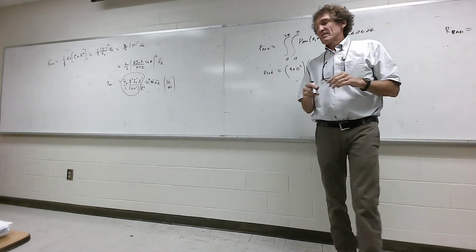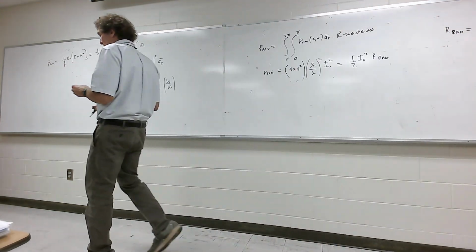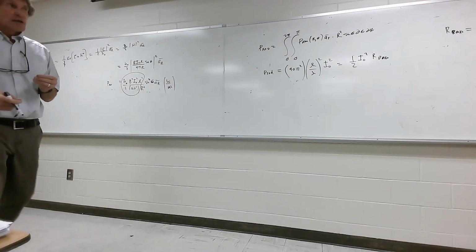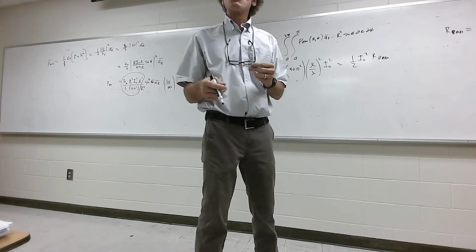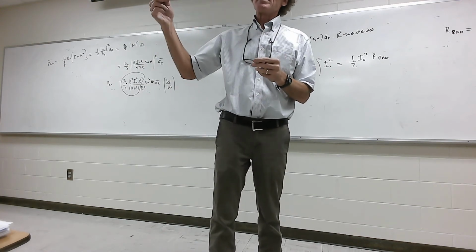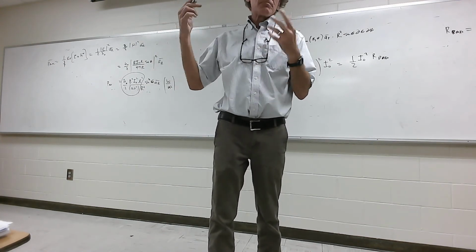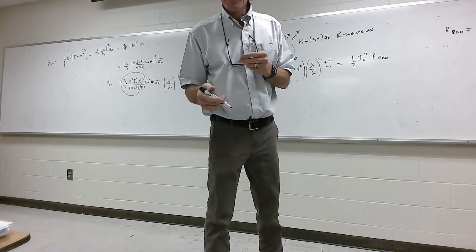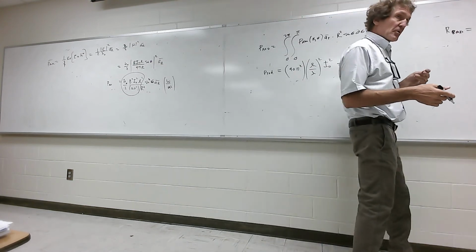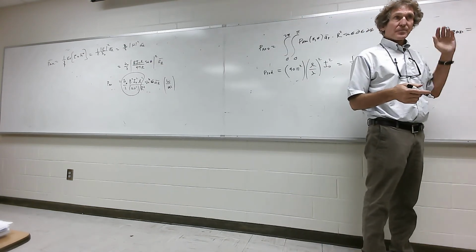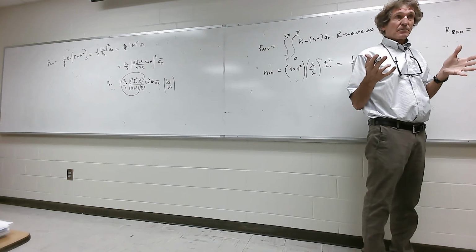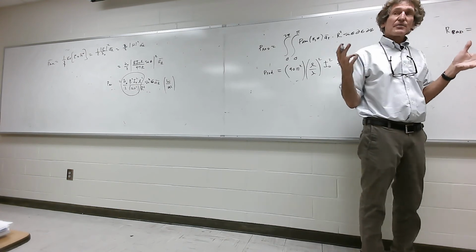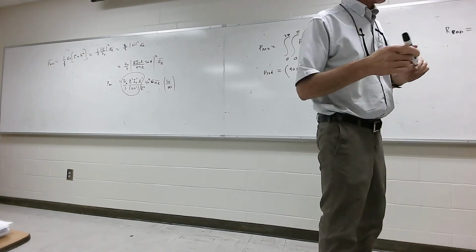First thing is, when you have any dipole, whatever the length, there's a radiation resistance. However, that radiation resistance may be much smaller than the actual reactance. You're going to have a plus J reactance. It's really going to be due to the inductance of the antenna. Usually, the inductance of a short antenna is going to dominate the actual value of the input impedance. It's going to be mainly reactive. Do y'all follow me? And dipole antennas, or short dipoles, are poor radiators.